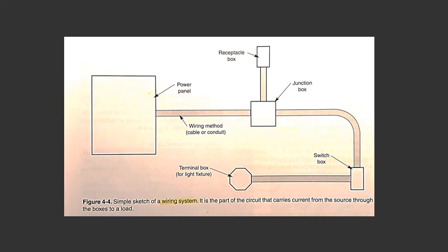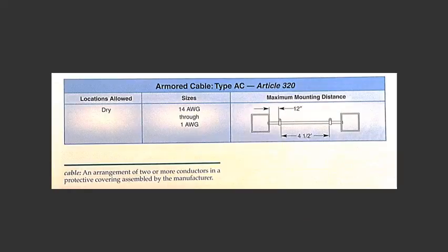The wiring system selected depends on the type of dwelling or style, materials and types of construction used, such as log, concrete, post and beam, or platform, surroundings of dwelling: hot, cold, wet or dry, cost of electrical materials, contractor's preference, building code requirements, and the preference of the owner or the client.